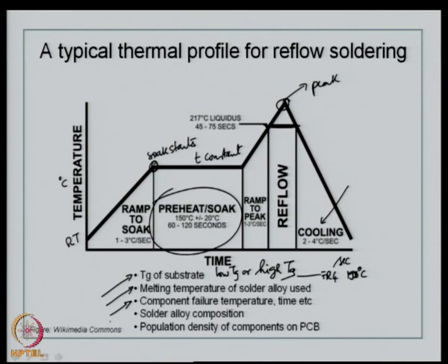So, in such cases you have to be very careful in deciding the peak reflow or choosing the right type of solder paste for mounting that component, or if it is only a single component in the entire batch, then you can do a hand soldering of that component if it is feasible. Otherwise, these considerations become very important.